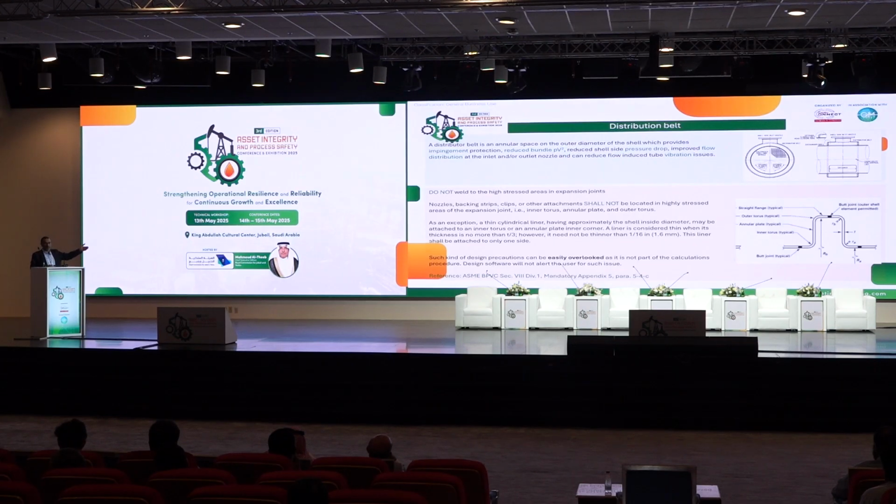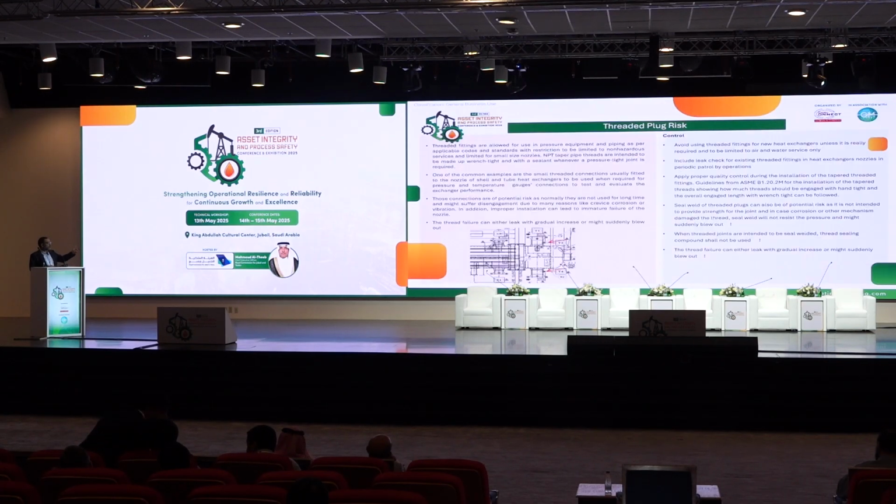And why was it missed? Because this is not one part of the design process or design procedure. So if you are using software, for example, for the design of the equipment, this will not be caught. This is mainly by experience, because it's not part of the normal process calculation. And there is the risk of threaded plugs in the heat exchangers, which are still used in many exchangers while it's not really required. And in many cases, it is one of the things impacting the plant by causing a leak.